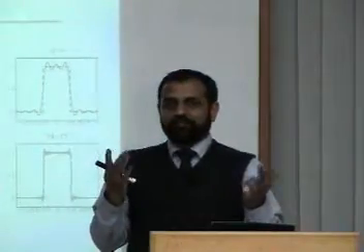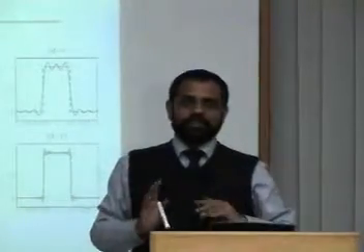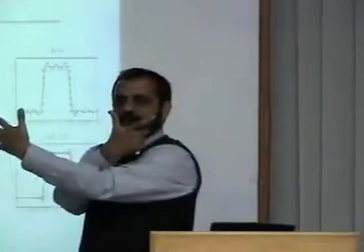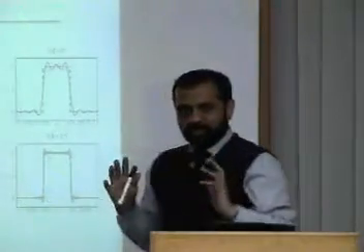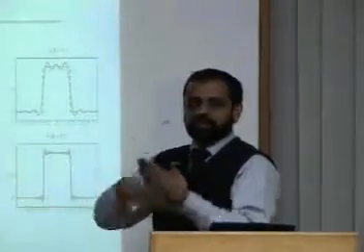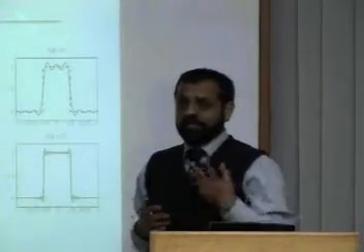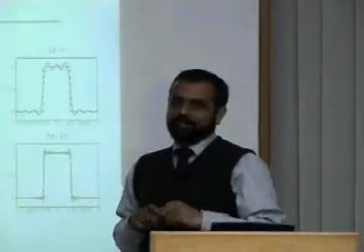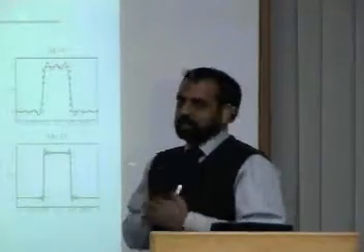And once you get a full overlap, how many samples do you need? The first time you see a full overlap is once you have 71 input samples. So 70 samples will be garbage, the partial overlap. Remember, this is your impulse response, and the signal you started and you just keep moving. Once your pipeline is filled, all the delay line is filled, only then you start getting the good samples. There will be a delay of 70 samples, which is inherent. I already told you earlier in the course that delay is inherent in signal processing because it's a processing delay and the system requires the previous samples to compute an output sample. That's why there will be delay.